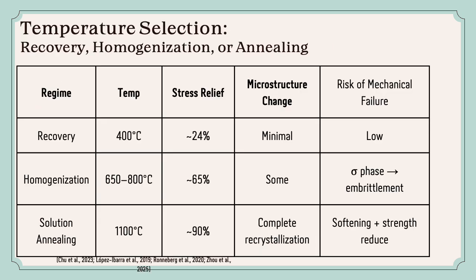Different heat treatment temperatures produce different effects on LPBF 316L. At 400 degrees Celsius, recovery occurs with minimal microstructure change. Although only about 24% of the residual stress is relieved, the risk of mechanical failure remains low.